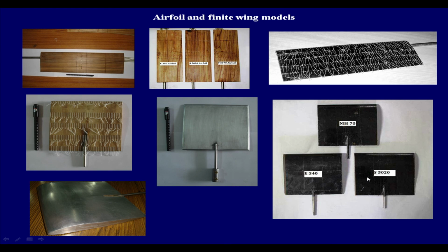You could have a large number of airfoils and finite wings to test depending on your interest. So here we have put up a few. You can see that some of the models are made out of metal, some are made out of wood. There could be numerous issues in the decision making, but ultimately one thing that matters in a big way is you have to ensure that you have a reasonably smooth surface to deal with. Otherwise, the aerodynamic characteristics could be very different from what you can imagine.